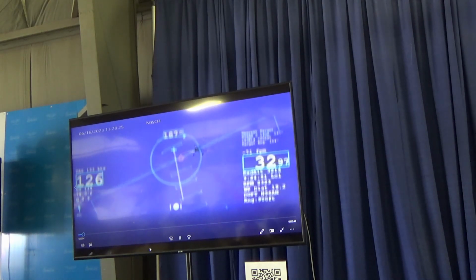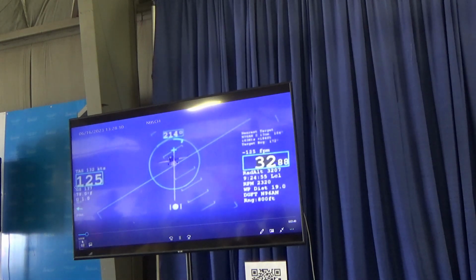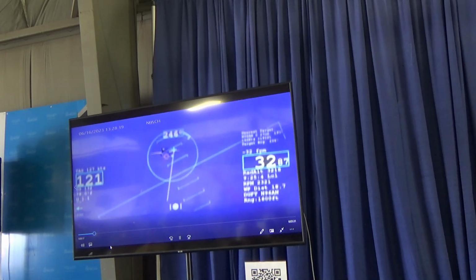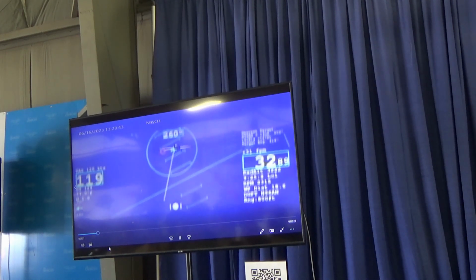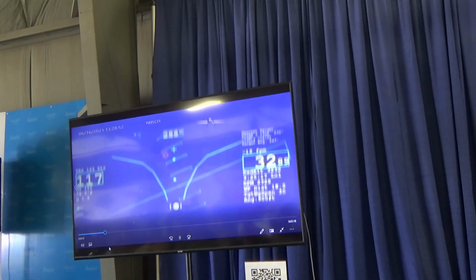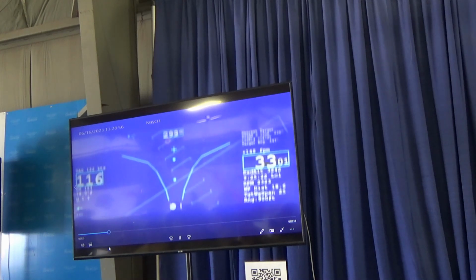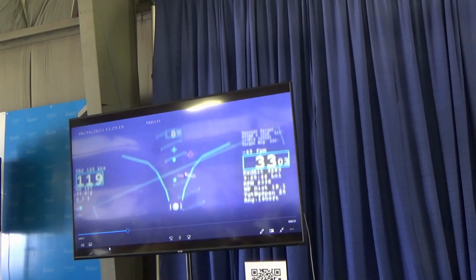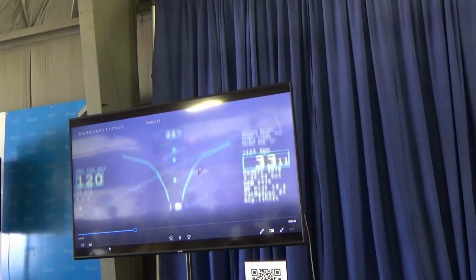Okay, this is my gun camera HUD picture. The audio's not making it out, but anyway, you can hear our AOA tone in the background in a turn here. That's what a gun funnel looks like. And the little dots represent a specific range with the wingspan inside of there. This vibration is causing the focus to be out a little. At different power settings, it'll be a pretty clear picture. Other times it'll get pretty bad.